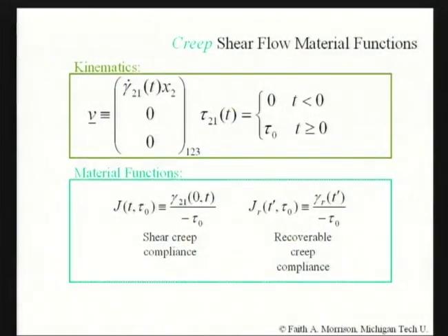Okay, what is creep? The last time I tried to show you the material function definition of creep, I left a lot of blanks here, and now all the blanks are filled in. Creep is a flow where there's no sigma dot here because I'm not actually going to specify the strain rate function. I'm instead going to specify that we impose a constant stress in a startup fashion. So at time t less than 0, the flow's not moving. Once it's time t equals 0, I apply a stress as if I put that weight on my sample.